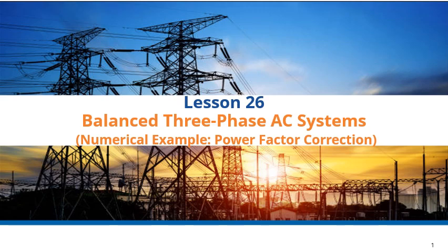In this lesson, starting with the circuit of lesson 25B, I will show the use of power capacitors to improve the power factor of the load, and we'll go over improvements that result from raising the power factor in terms of increased efficiency and decreased power loss, and of lowering of the voltage drop.